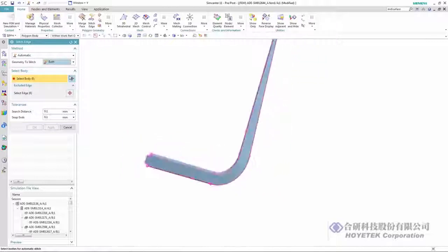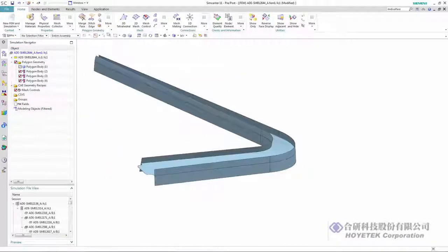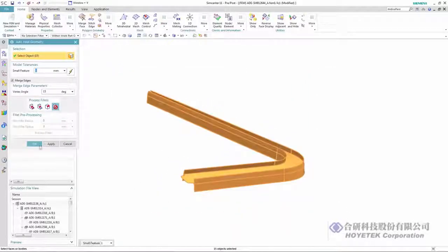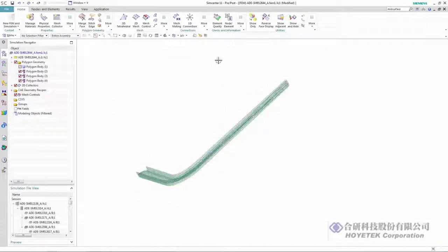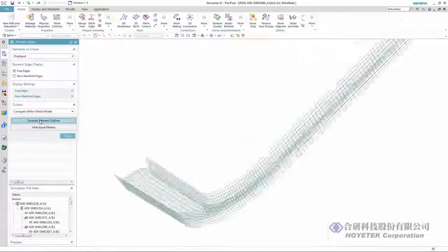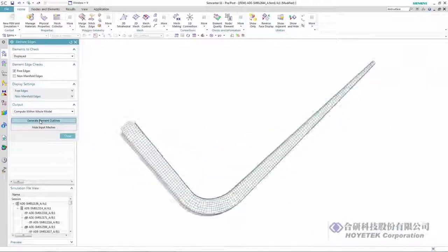In other CAE tools, this would be a manually intensive process involving meshing existing unstitched geometry and then reconnecting nodes and elements one by one. In an integrated solution such as Simcenter 3D, the CAE engineer instead fixes the geometry prior to meshing and can also use geometry cleanup tools to further improve the quality of the mesh, and hence the accuracy of the CAE results.